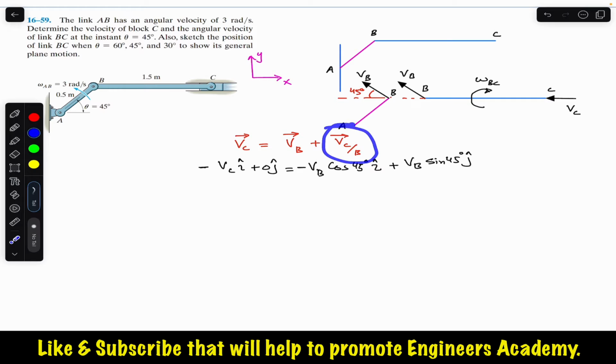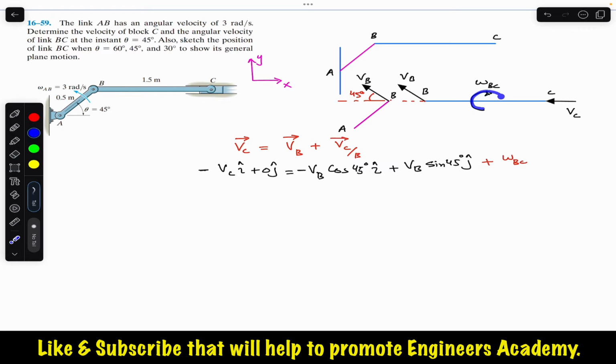Similarly, we always know that the relative velocity of C relative to B is due to this omega BC, right? Due to the angular velocity of link BC. So we can always write this velocity as plus omega BC. And if we are assuming that omega BC is in the clockwise direction, so if we curl our right hand fingers in the clockwise direction, the thumb will point towards the screen. Towards the screen is the negative k direction. So we will write minus k.